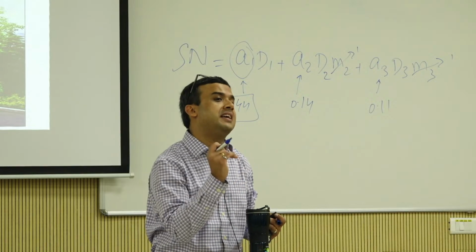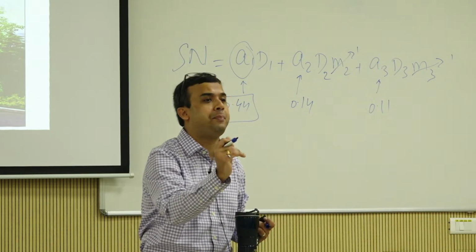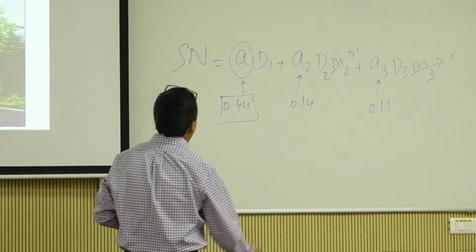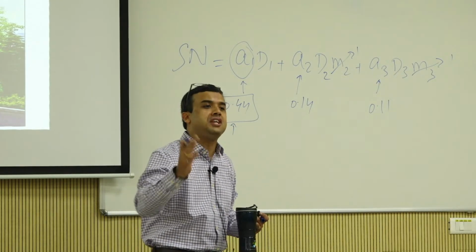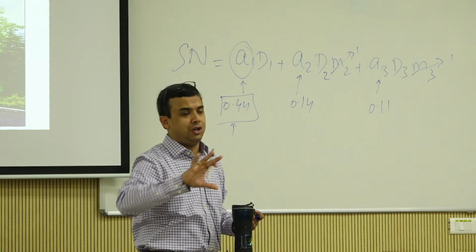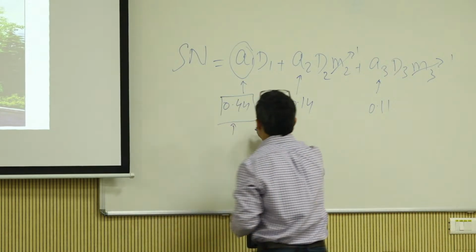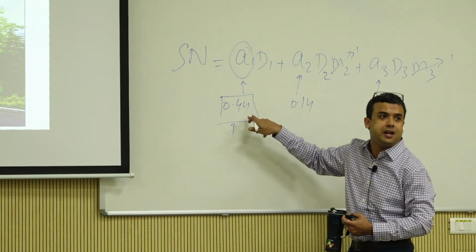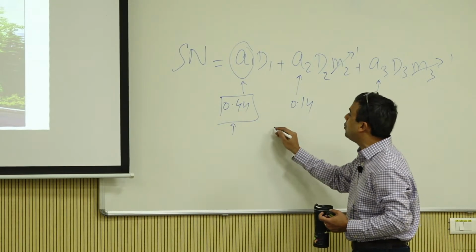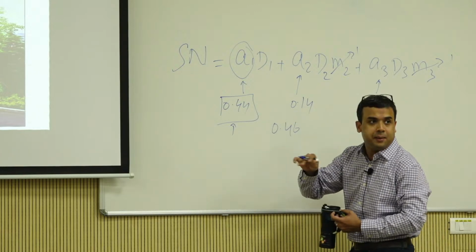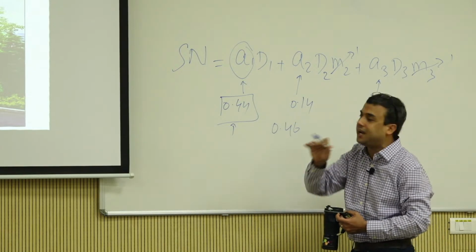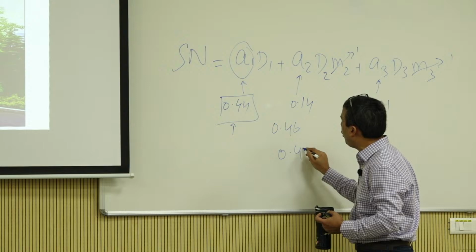How do you have a somewhat improved empirical design? Let's just say 0.44 is the base. Now say in the state of Odisha, you have done so much research and so much data collection. You can say, okay, use 0.44 in this kind of pavement. If I have a really good binder, really good mix, then maybe use 0.46. If you have really poor aggregate and everything, maybe make it 0.4.